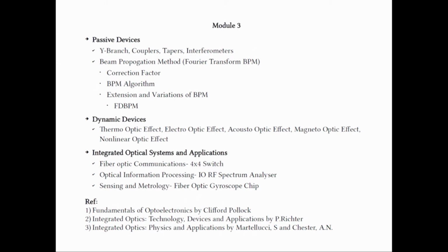So, nonlinear integrated optics effectively implies using the intensity of the light or the electric field of the light wave itself to change the properties, which in simpler terms translates down to the power dependent refractive index. If the refractive index is dependent on the input power, then it has different properties at different input powers, and so we can have a lot of nonlinear effects.